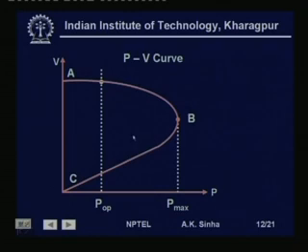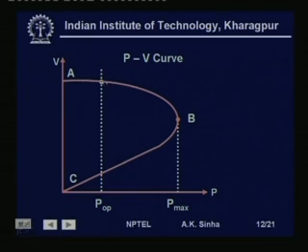This is a curve for a constant impedance load. But if we have a constant power load, which is there in most of the cases, then this curve will have a further larger dip taking place. Here what we see is, as we reach near this maximum point, the slope of the curve becomes larger and larger, and at this point it is highest.